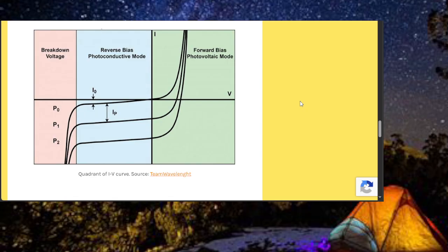We want this thing to operate at a certain current level, and I believe each one of those curves may represent a different voltage level. If the voltage gets more negative, this current will increase. Well, no, actually the current stays the same. No matter what the voltage, this reverse bias current stays the same. And we believe we've calculated about 3 microamps on one of those LEDs.